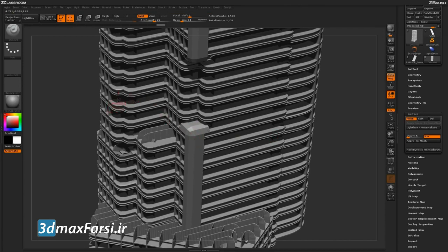And you can see everywhere on that actual model where I had those harsh edges on the lower version, since they're all welded together, the normals are creating this kind of smooth nature to your mesh. So if you want to have areas in your model that are not getting this smooth effect, we just need to come through and detach those faces.